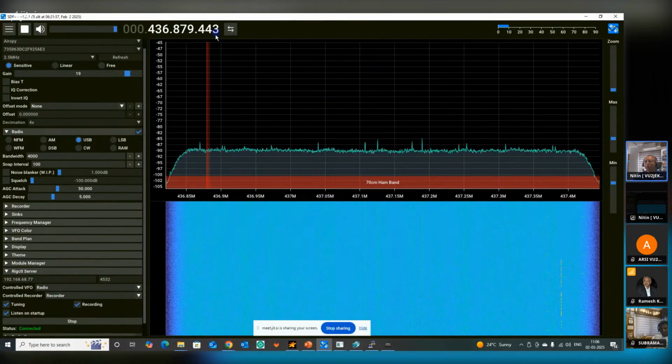But when you are using an FM satellite, you will have to manually compensate for the Doppler. All you can do is store those frequencies in various memories, and then toggle between that memory to give that 5 kHz Doppler correction.